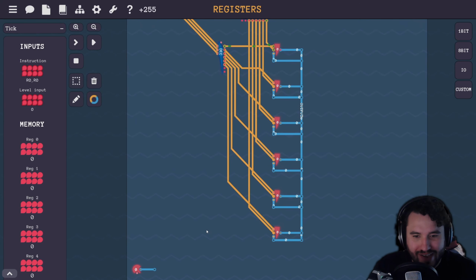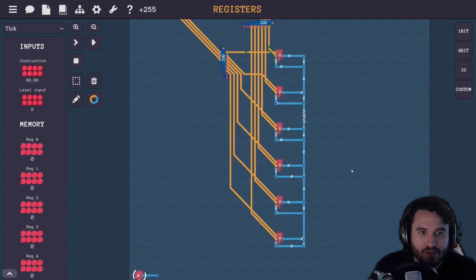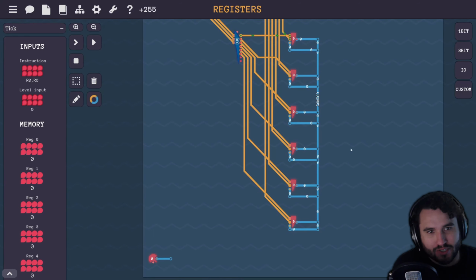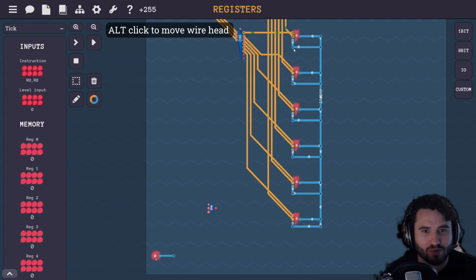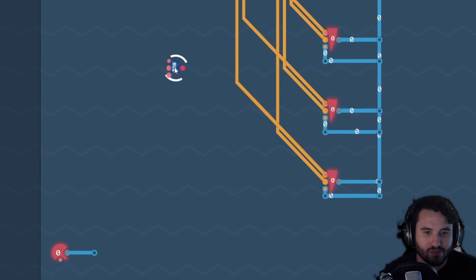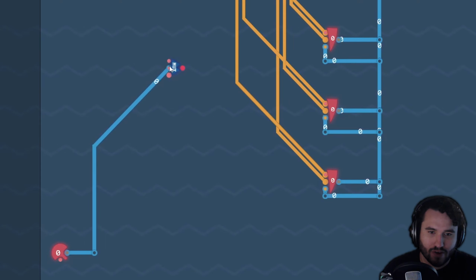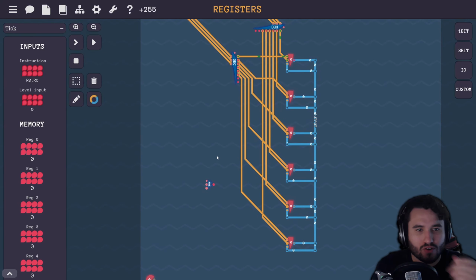What makes this just a tad more challenging, however, is that we now have to select between a value from this bus or one of these input values for what gets passed in. So we're going to have to add a selection between the 2 of those. So we will need a multiplexer in here as well. We'll get our 8-bit mux. And for each of these inputs, it actually needs to be the output of this multiplexer. And this multiplexer is going to have the output bus and this input value here that it's selecting between. So give me 1 second and let me hook all that up.